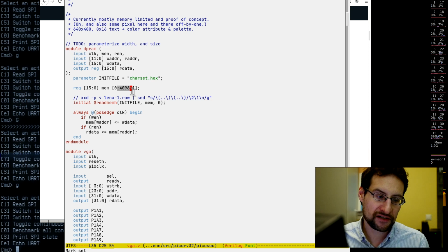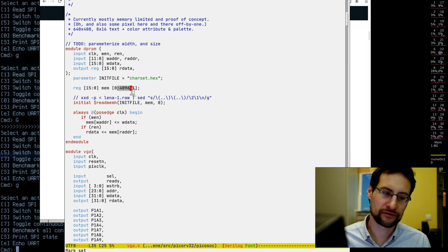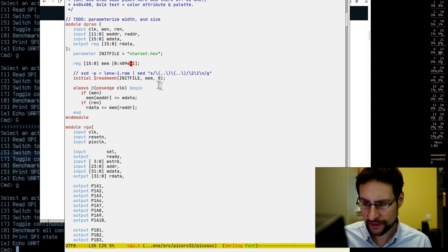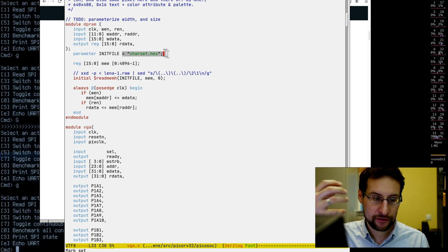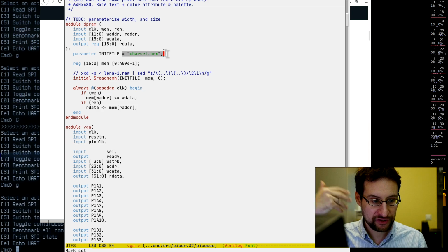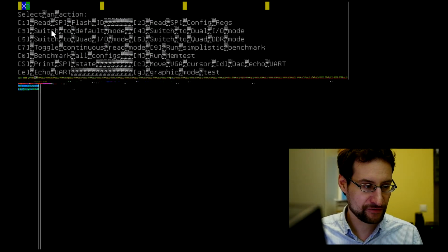Maybe these are the things like, now everything is working, we can also make it a little bit prettier. Initialize here with some memory. I have here some parameter now for that. This is just so that the FPGA comes up with a correct character set loaded into the character memory for exactly these pixels, not to be garbage. We can also actually reset this, as you see then.